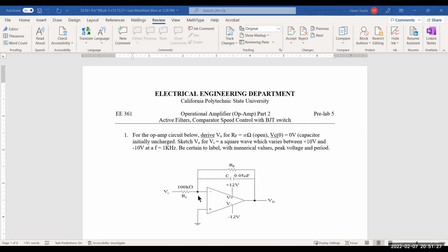It is the same function that the capacitor is performing in this op-amp circuit. This is known as an active filter versus a passive filter, which is only R and C. The active component is the op-amp. So you not only have filtering from the RC components, but you also have active gain from the op-amp circuit.